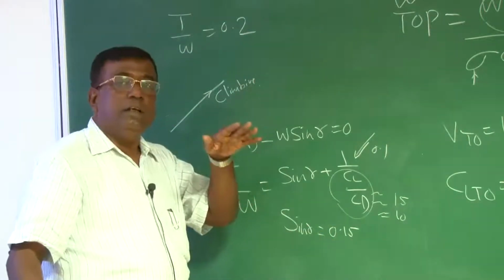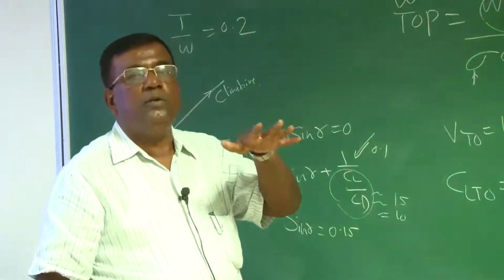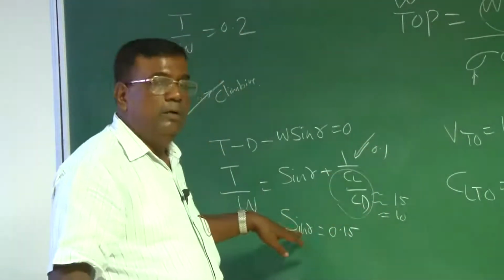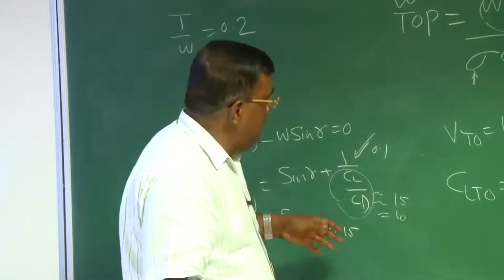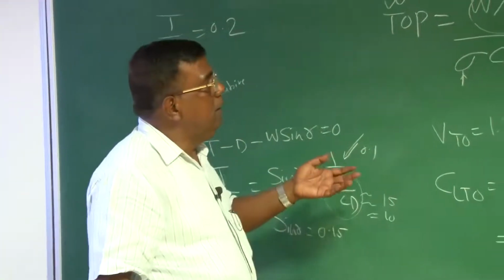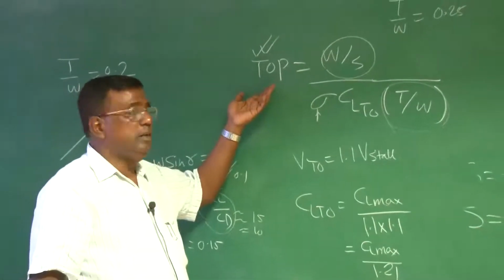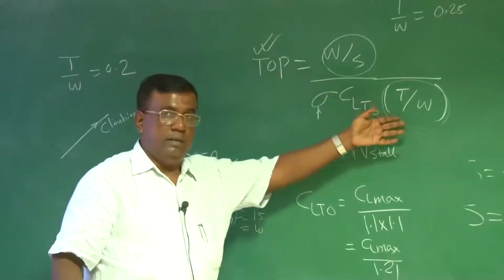You have to see, generally for normal aircraft we will prefer an initial climb of 7 to 8 degrees. Okay? So all those things go into your mind. And if you find that with the T by W I have selected, I am not really getting a realistic number for 1,000 feet or 6,000 feet land roll distance, then you can increase this.